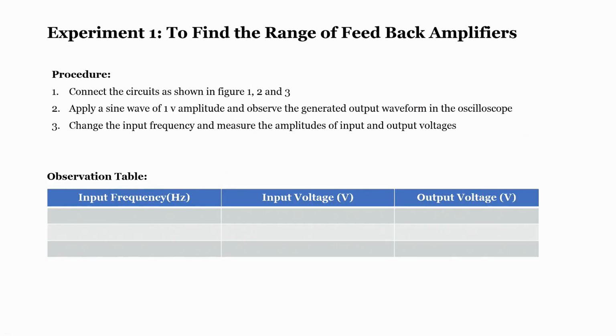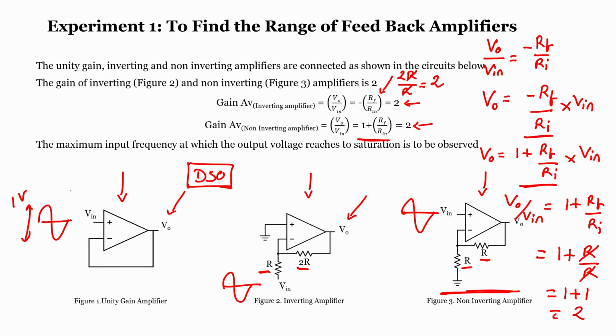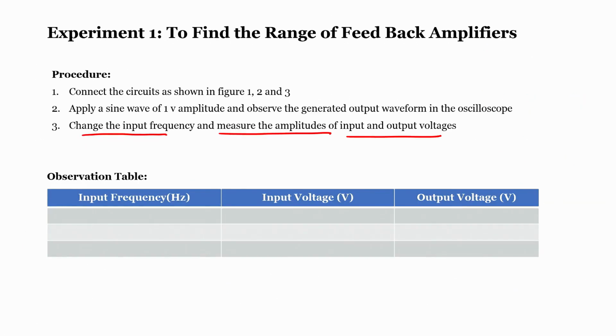Then change the input frequency and measure the amplitudes of the input and output voltages. If I change my frequency here, I need to measure the change in my input and output voltage, that is the third step. So, if you see here, what will we do?